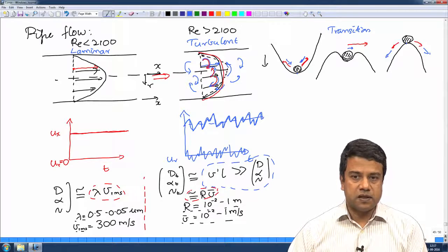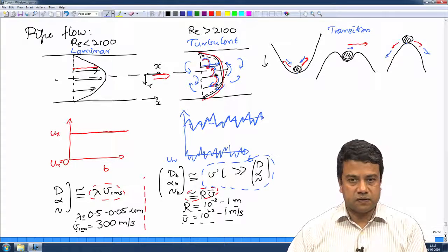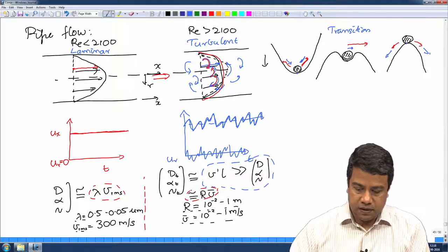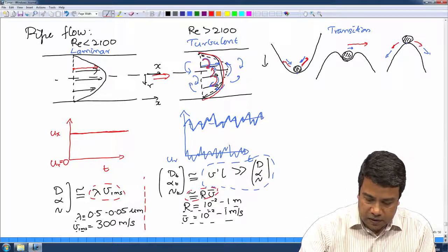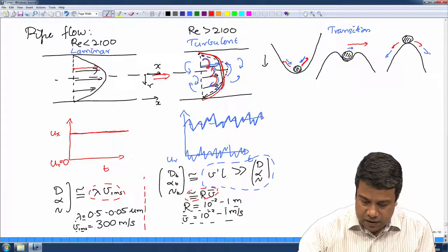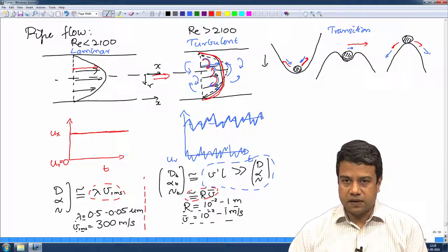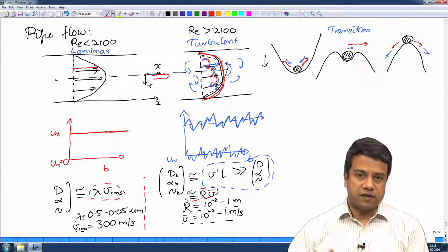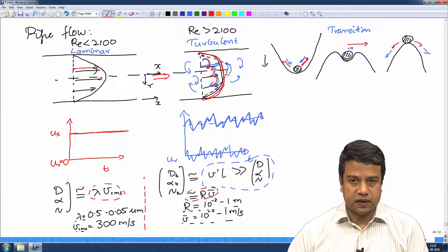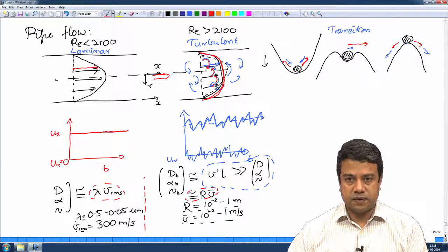And that fluid velocity is what transports momentum across the flow primarily. The velocity profile, if you plot it, looks flatter at the center and steeper close to the walls. At the walls itself, the velocity has to be 0. All components of the velocity have to be 0.